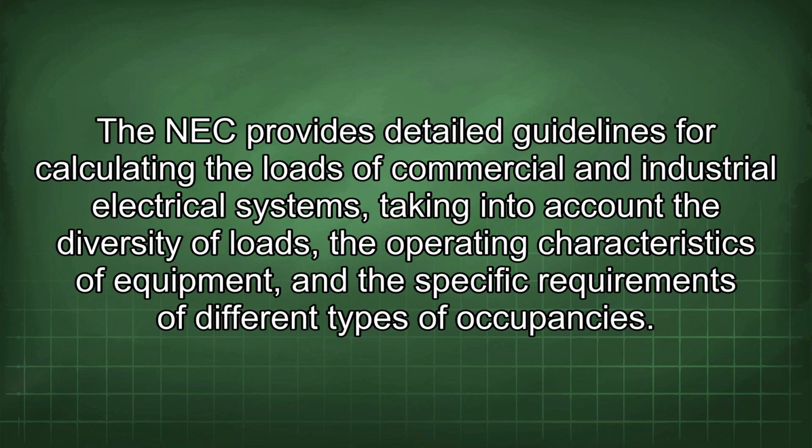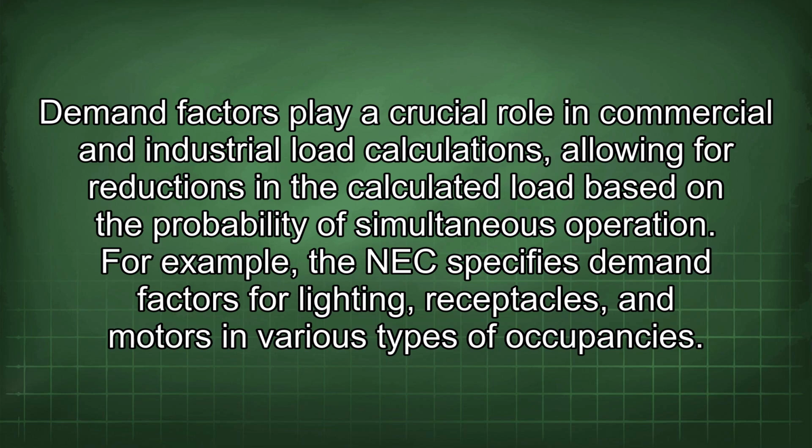The NEC provides detailed guidelines for calculating the loads of commercial and industrial electrical systems, taking into account the diversity of loads, the operating characteristics of equipment, and the specific requirements of different types of occupancies. Demand factors play a crucial role in commercial and industrial load calculations, allowing for reductions in the calculated load based on the probability of simultaneous operation.